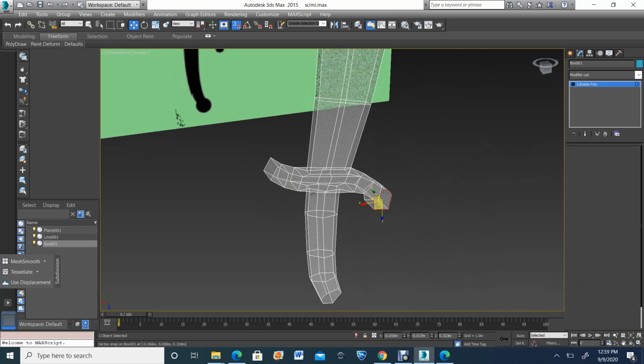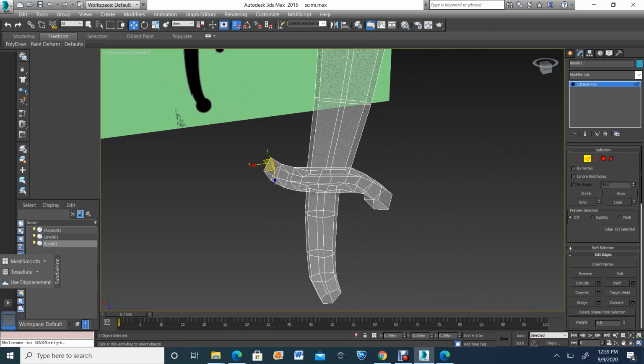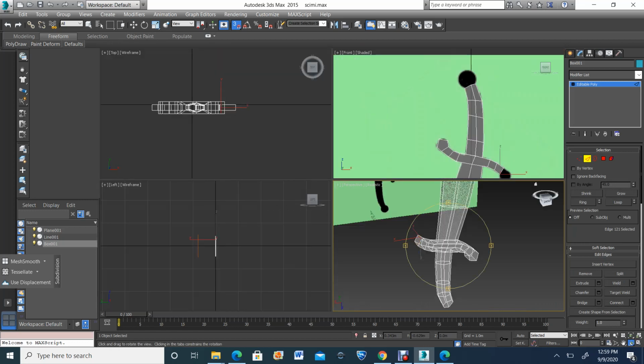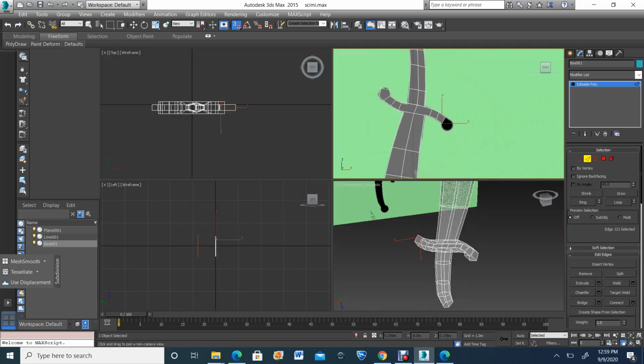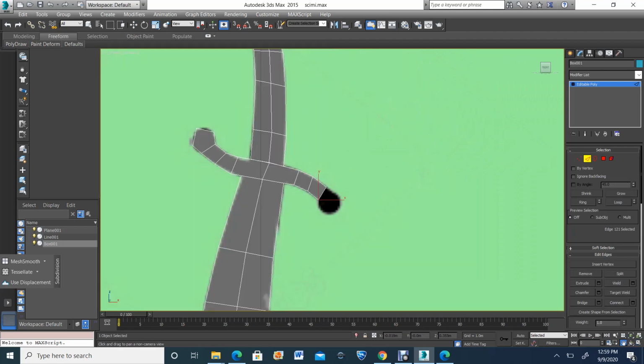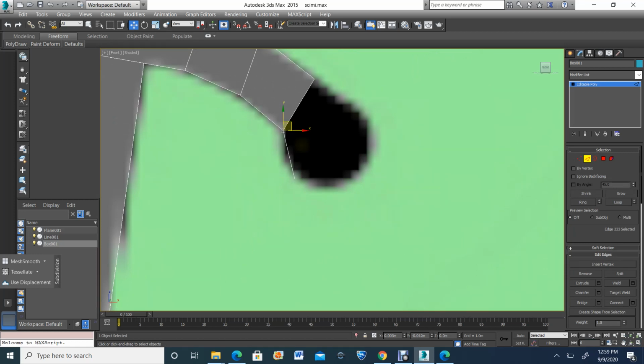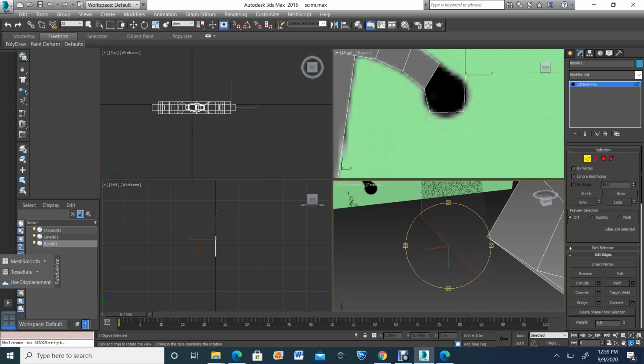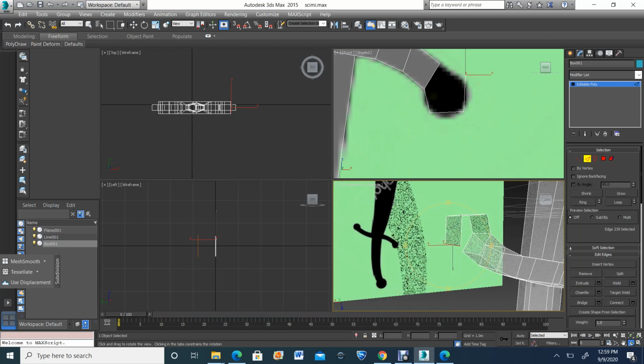And now we're going to do the extrusion for the other one. So get out of that view again. Make sure your snapping is off because that'll screw up your mesh if you snap in 3D. Zoom in and then extrusion 1, 2, 3, and oh no, that's the last one. So that's the one I want to snap. So I'm going to go Z, turn S to snap again. Oh, and hold Shift.